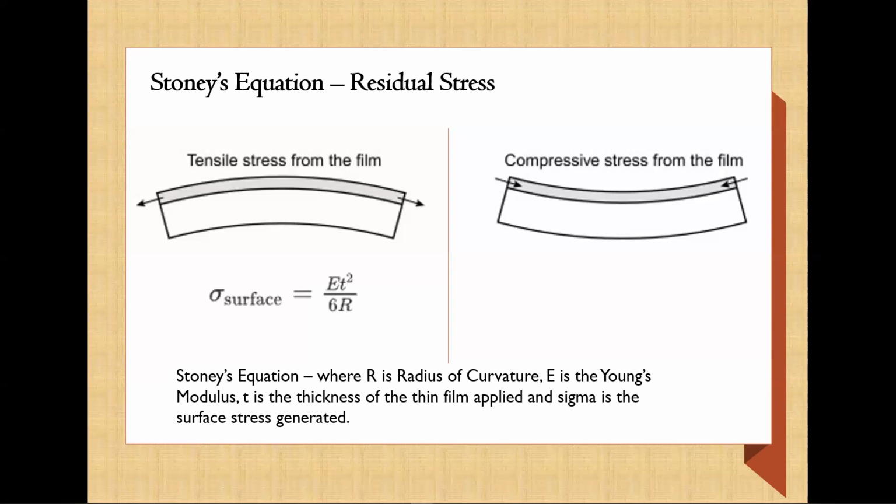And so this process has been the technique of choice to measure both tensile and compressive stress induced, as well as the layer by layer introduction of the two types of stresses for specific applications. Possibly if you have a tensile compressive tensile, or compressive tensile compressive, or just any form of stress gradient in the surface here.